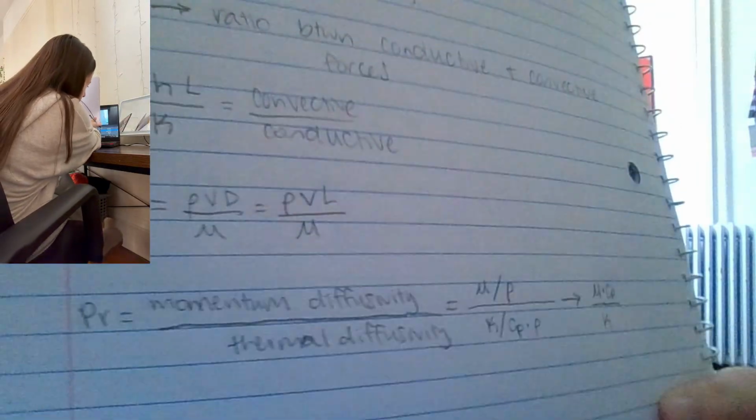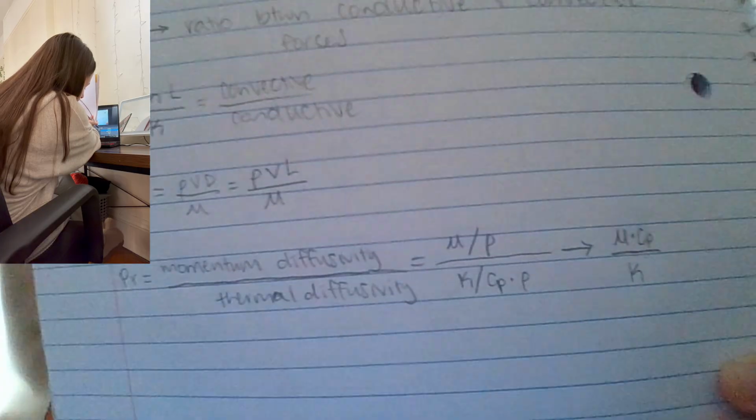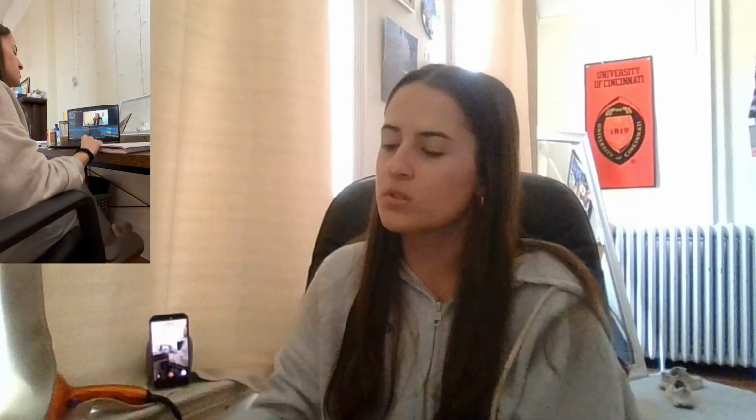So that's what we have for Prandtl's number. So now we can plug these units back into Nusselt's number in order to find out how we can maximize the sort of flow that we're getting across this flat surface. So now we're going to plug in all of these values that we found for everything back into the Nusselt equation. So once again, Nu x equals 0.332, Reynolds number to the 1/2, Prandtl's number to the 1/3.